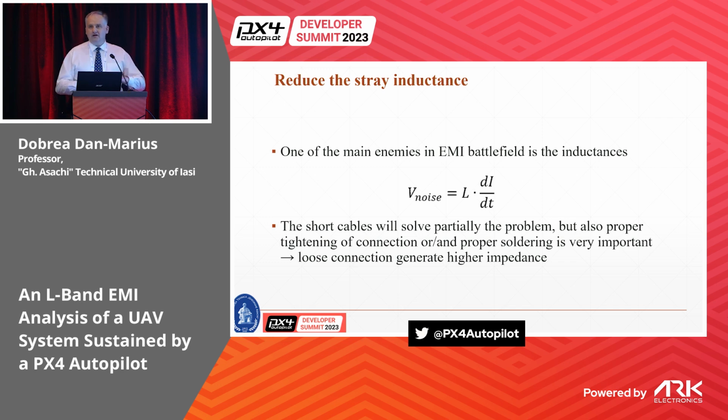When you have higher currents that change value in a short time interval, you'll get higher noise levels. One solution is to use short cables, but it's also important to tighten the connectors and have better soldering in order to decrease the stray inductance.